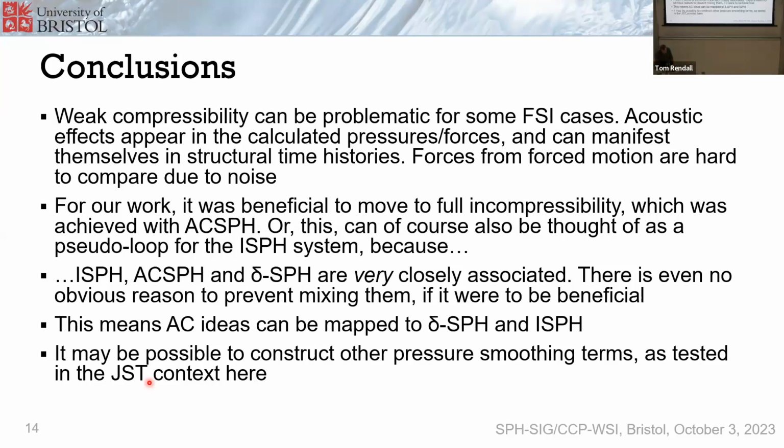So the flexible bottom still water case. My first real exposure to it was during a solar program, solar project. And it really struck me that we have lots of people using volume of fluid method in that project, as well as people using SPH. The volume of fluid folks looked at them and said, why do you want to do that? Of course, it's just going to sit there. And the SPH people went, it's pretty difficult. So I think the fact that you've managed to get to the point where you've got a solution that for that case is comparable to the VOF solution